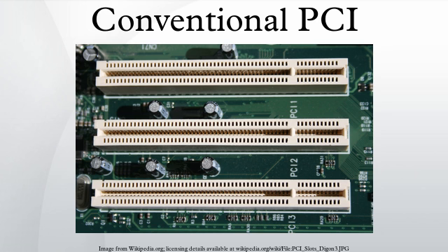Disconnect with data: if the target asserts STOP and TRDY at the same time, this indicates that the target wishes this to be the last data phase. For example, a target that does not support burst transfers will always do this, turning bursts into single-word PCI transactions. This is the most efficient way for a target to end a burst.